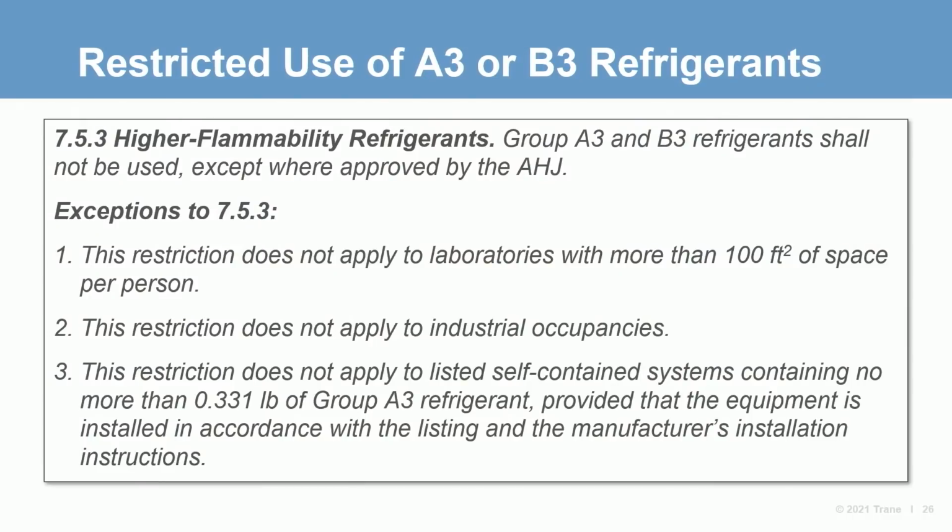First, the standard restricts the use of Group A3 or B3 flammable refrigerants to only a few exempt applications. Certain laboratories and industrial occupancies are exempt, as are small self-contained systems such as vending machines, refrigerators, or water coolers, as long as the refrigerant charge is very, very small.